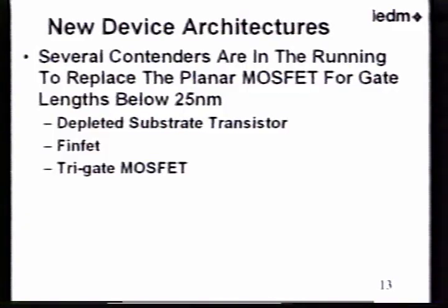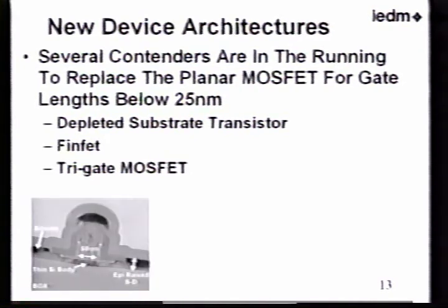The architectures themselves will also have to change. I showed earlier a very standard metal oxide semiconductor transistor, very traditional type of design, but even it is running into limitations. And we've seen a number of different devices proposed and will be talked about certainly at this conference, have been proposed at this conference in the past. One of them, a depleted substrate transistor, instead of building the transistor on this large bulk of silicon, controlling the body, the depth, the bulk region with a very thin silicon body.